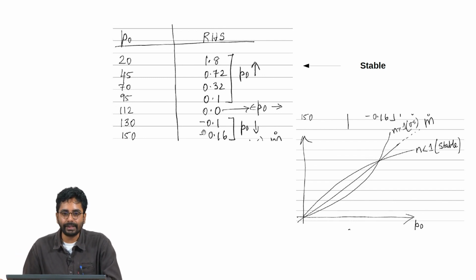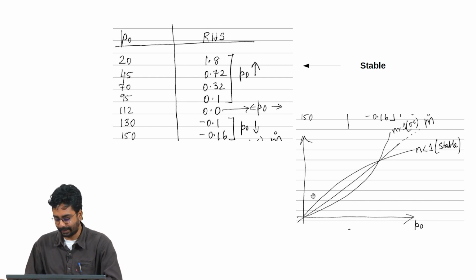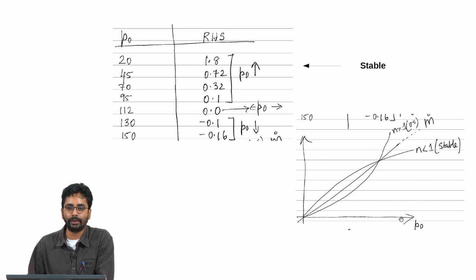This equilibrium state, where dPc/dt is 0, can be stable or it can be unstable. What I mean by that is, look at the graphs I have shown on the bottom right. It is a plot of chamber pressure versus m dot in and m dot out. Remember that m dot out goes as Pc At by C star, therefore for a fixed throat and a fixed propellant composition, the exit mass flow rate will increase linearly with pressure, and that is what I have shown with the line in the center.